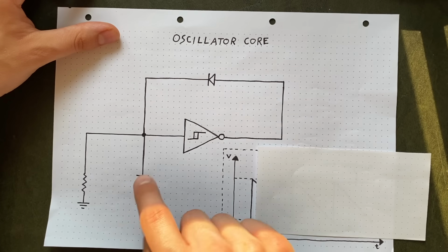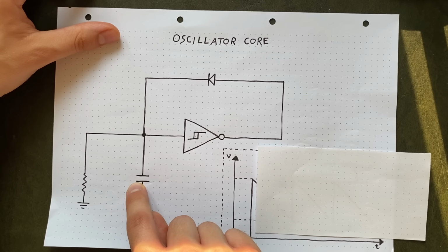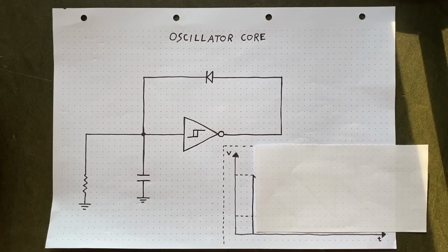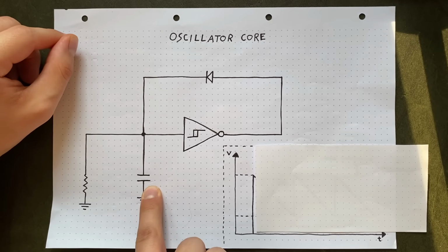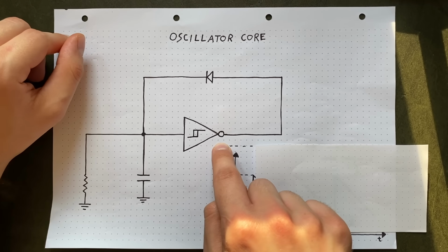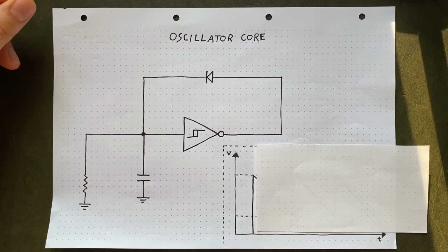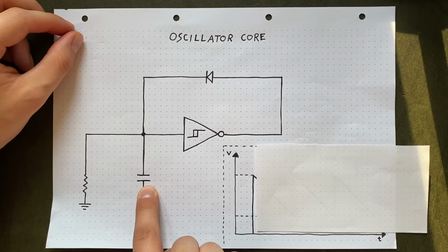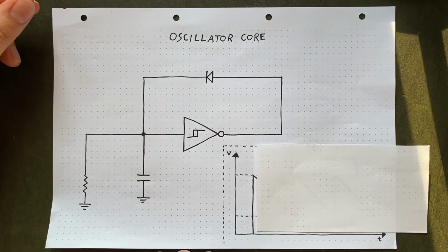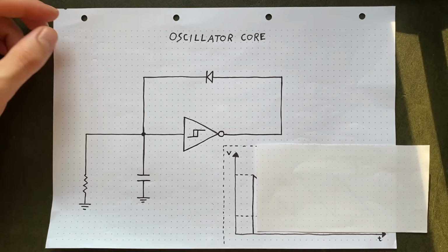So as a reaction, the pump will instantly stop working once the capacitor is charged and the pressure passes the sensor's upper threshold. So let's assume we're in this state now. The capacitor is charged enough so that the sensor here tells the pump to shut down. This means that no water is being pushed through our diode anymore, which in turn means that our capacitor has no opposing force anymore. We've essentially stopped pushing water into it, so our balloon will push its contents back into the system. And where does the water go?